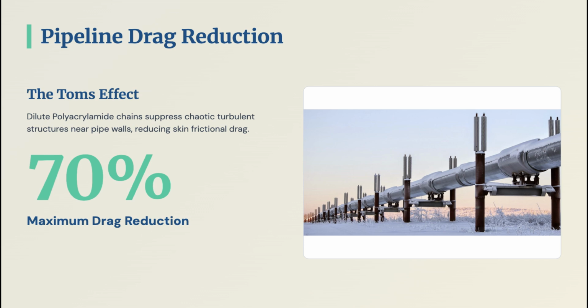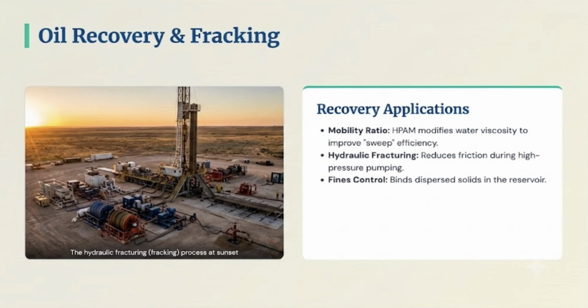In hydraulic fracturing operations, friction reducer formulas deploy highly diluted polyacrylamide to minimize pumping pressure during the initial pad and slurry injection stages. Typical dosages range from tens to hundreds of parts per million, carefully adjusted based on real-time water chemistry and proppant sand loading. In specialized scenarios, higher dedicated dosages may be implemented. Mechanical shear degradation is strictly controlled by ensuring gentle mixing, properly inverting emulsions, and avoiding excessive recirculation within the pumps.